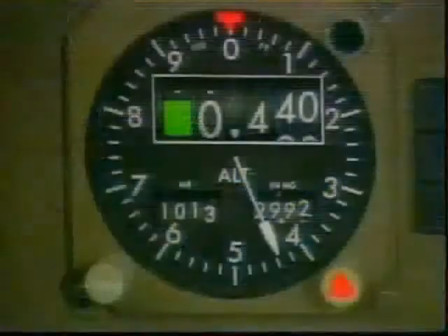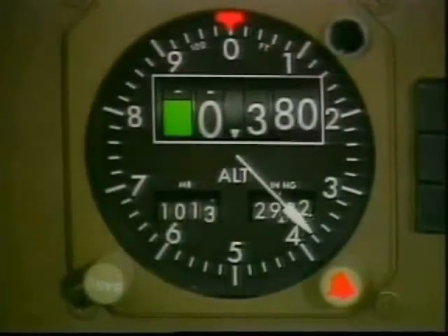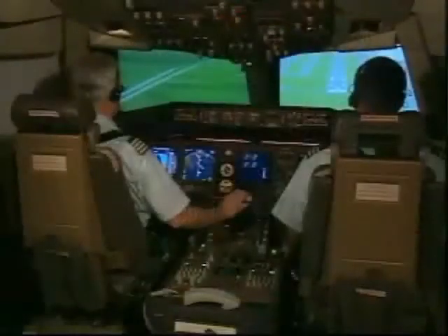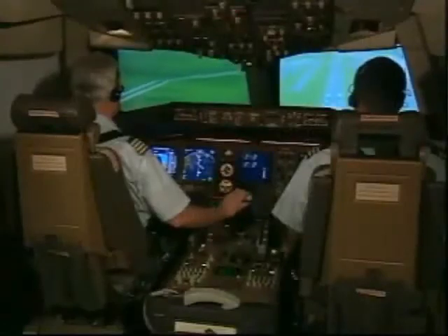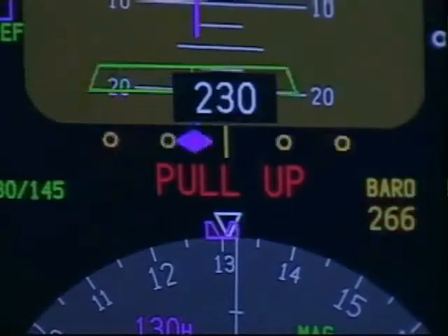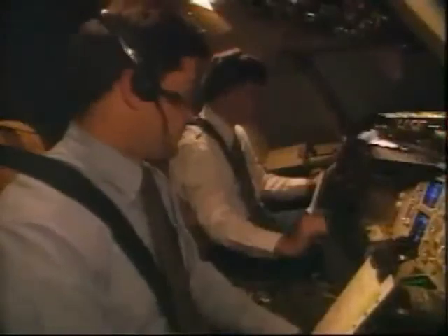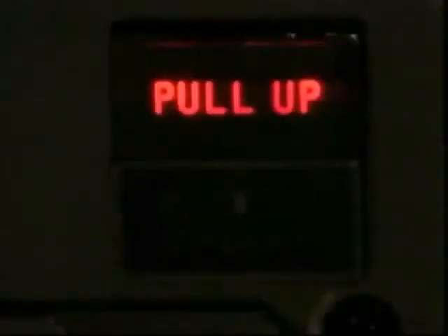As just mentioned, vertical situational awareness is your responsibility. If the ground proximity warning system alert sounds, you must be prepared to execute an immediate pull-up. Except in clear daylight visual conditions, the flight crew should immediately, and without hesitating to evaluate the warning, execute the pull-up action recommended in their company's procedure manual.